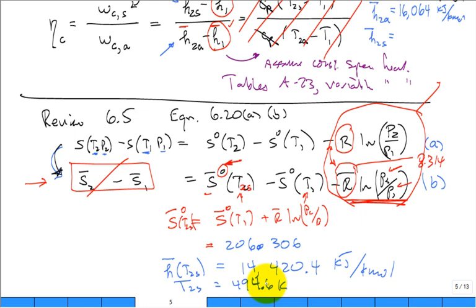All right, so then I finally get this H bars. We come up to this equation. We calculate the compressor isentropic efficiency. Let's go ahead and put in some numbers. 14,420 minus, what was my H1? 7,266. 7,266 divided by 16,064 minus 7,266, and you get the efficiency of 81.3%.